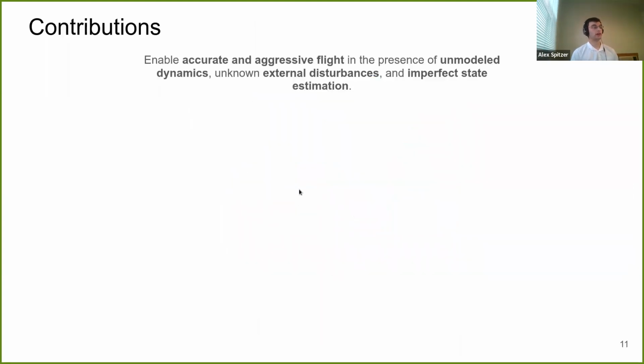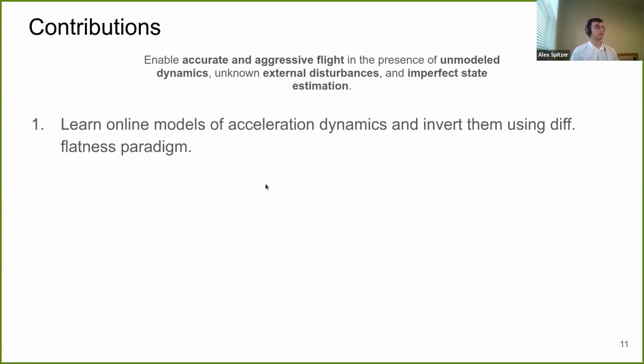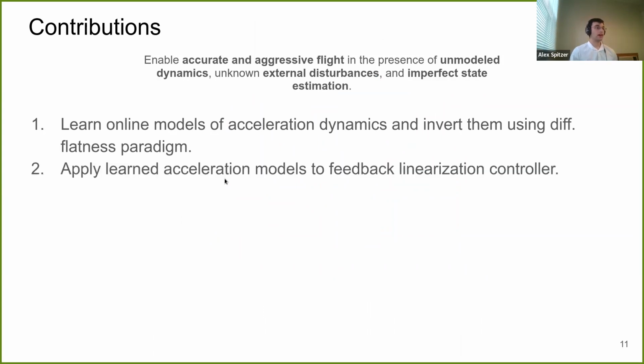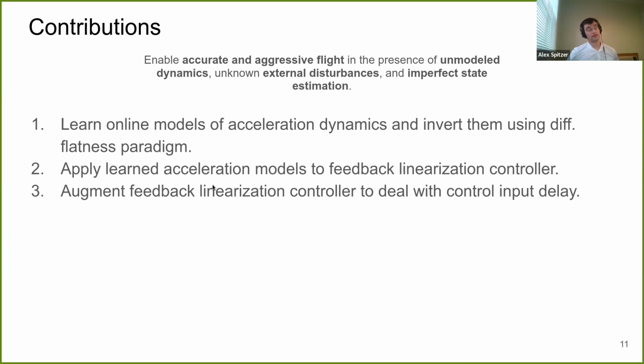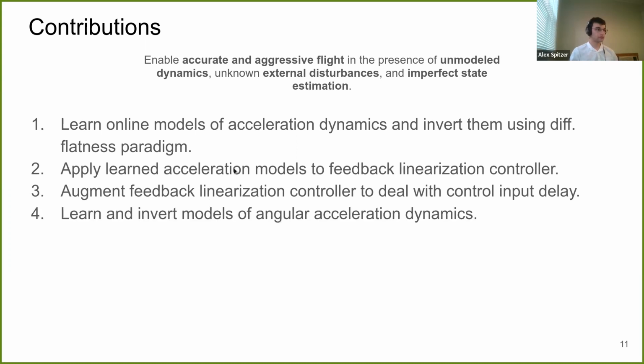So quickly, I'm going to list the contributions of the thesis, and then we'll get into it. So we learn accurate models of acceleration dynamics, and we invert them using the differential flatness paradigm. We then apply the learned acceleration models to the feedback linearization controller. We also augment this feedback linearization controller to deal with control input delay, improving the robustness of that controller.